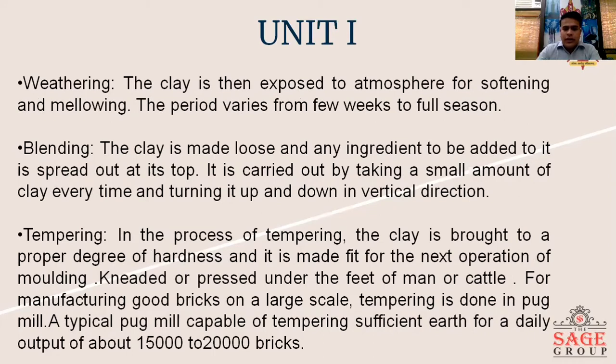Now weathering. The clay is then exposed to the atmosphere for softening or mellowing. The period varies from a few weeks to a full season. That means it is exposed to the atmosphere and gets softened, and it maintains the moisture, water and air level in the soil so that it can be mixed thoroughly and give a good quality of brick.